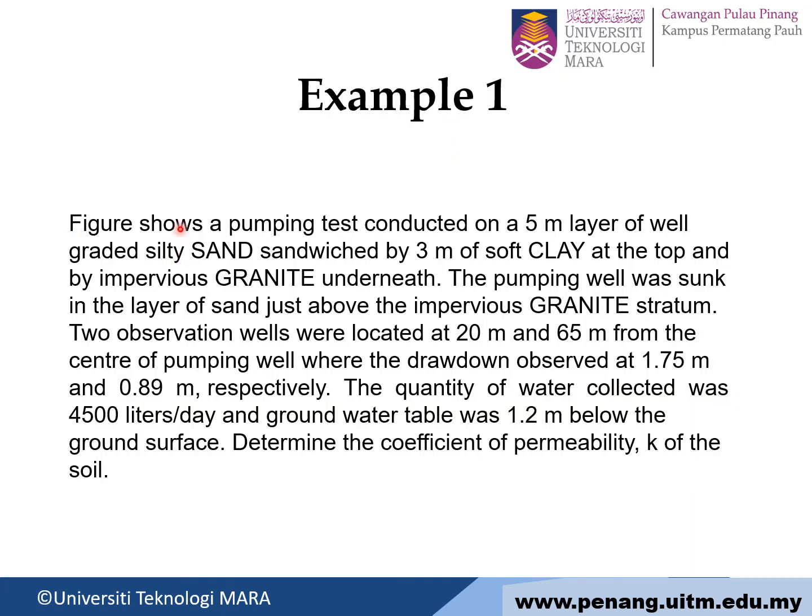Example 1. The figure shows a pumping test conducted on a 5-meter layer of well-graded silty sand sandwiched by 3 meters of soft clay at the top and by impervious granite underneath. The pumping well was sunk in the layer of sand just above the impervious granite stratum. 2 observation wells were located at 20 meters and 65 meters from the center of the pumping well.